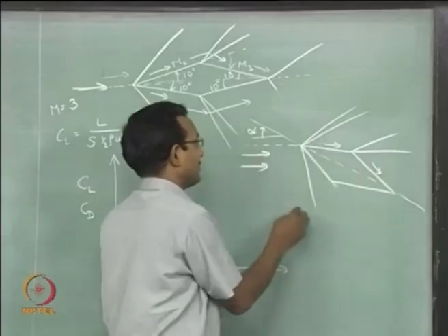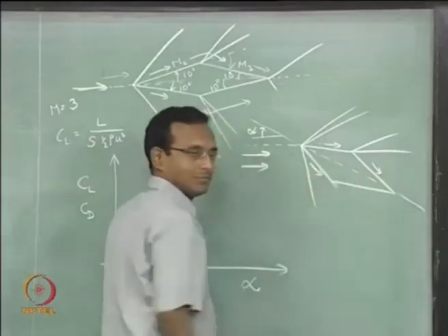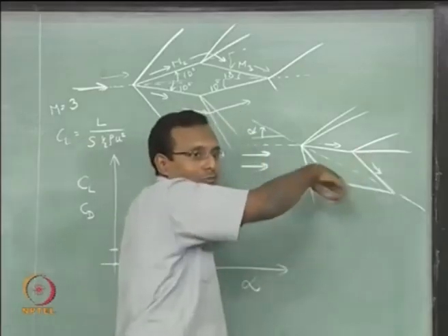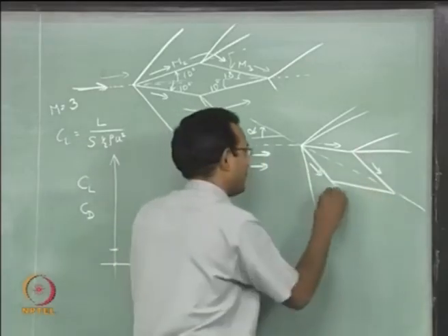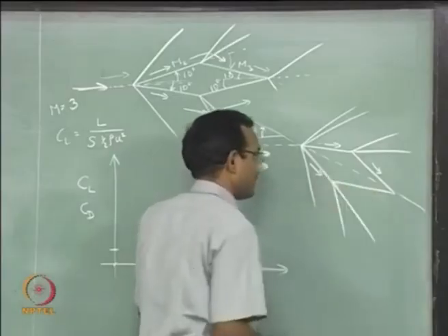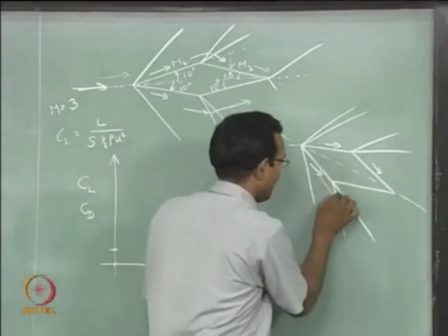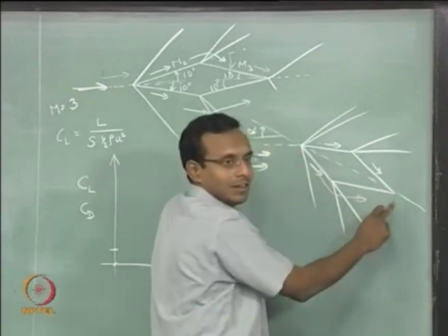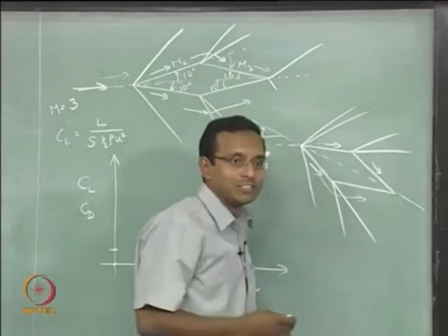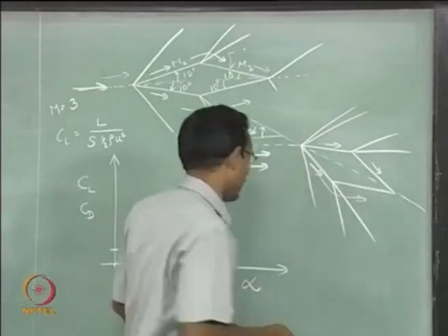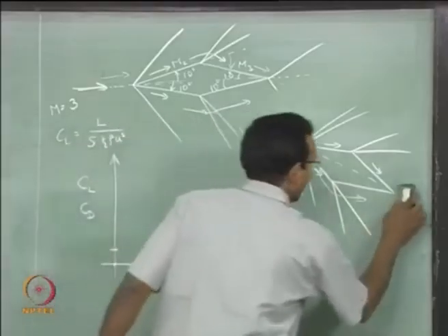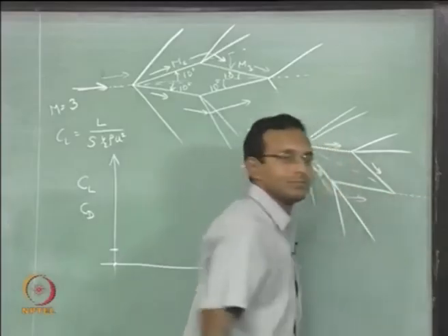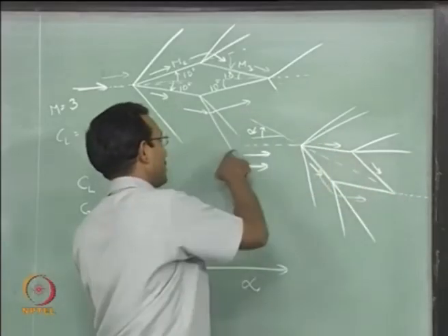Let us go on the bottom side. We have gone here, it is going along this. Now what will this see? The wall is going away from the flow, so it will be an expansion this way. Some expansion fan is going to turn from here to this direction. Now these two flows will meet, and I told you that the downwash is going to be really small, so I know that it is roughly going to be close to 0 angle with respect to the original flow direction.